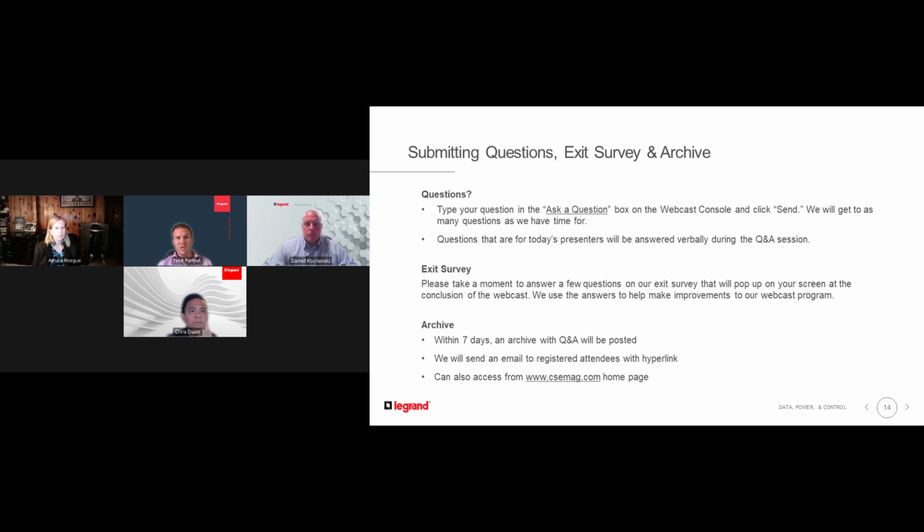What we've developed is a small little box. We call it a load bank box. They could actually be rented directly from Starline or purchased. Our rented units are smaller, only a 12 by 12 type of unit in inches. You'll put that up into the bus duct and spin it in no different than any other plug. It has a set of cam locks on there that you'll be able to connect into and connect to the load bank.